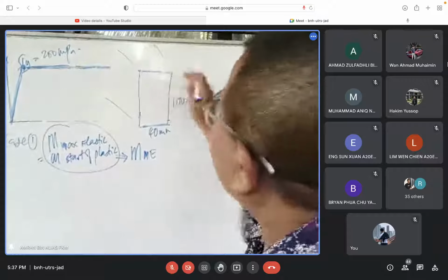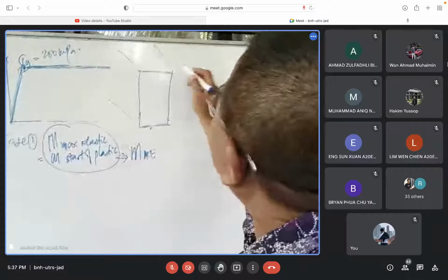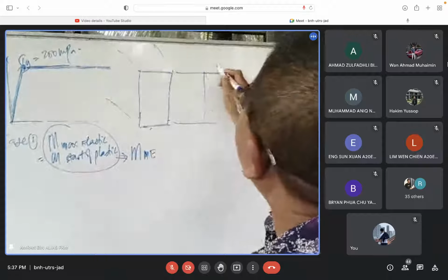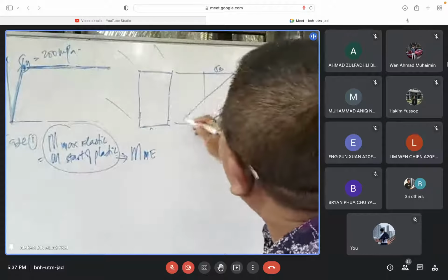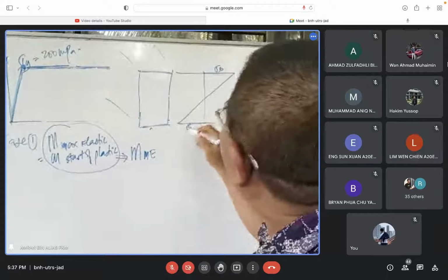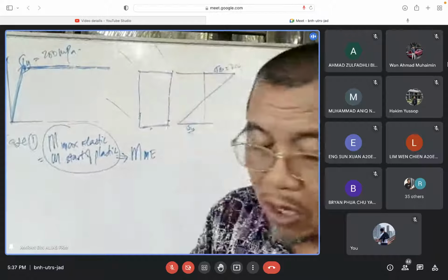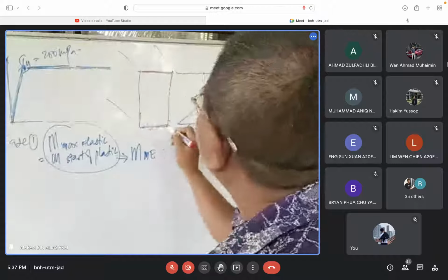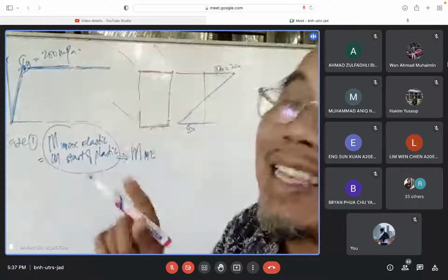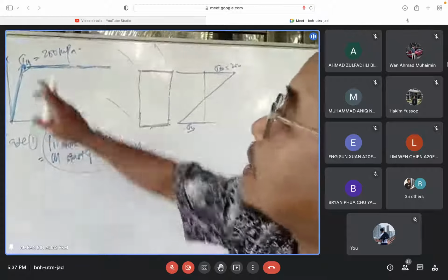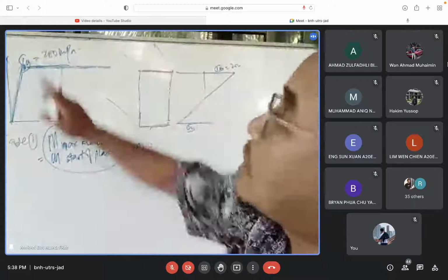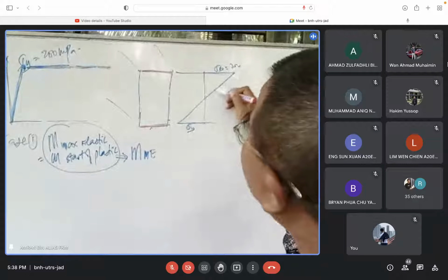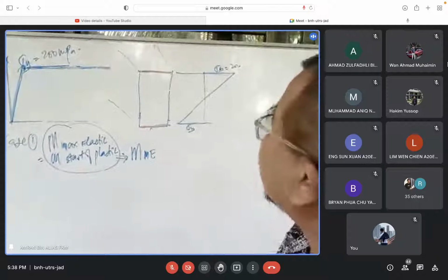And then this is the diagram here, the stress diagram side by side. So the stress here must be sigma y, and then a straight line there, and the stress here must be sigma y. This must be 200. Only one layer here is plastic. What is plastic? The stress there is 200. If the yield were 300, the stress would be 300. For this case, the yield is 200, so the stress is 200. The other is less than 200. So this is the diagram of the stress.